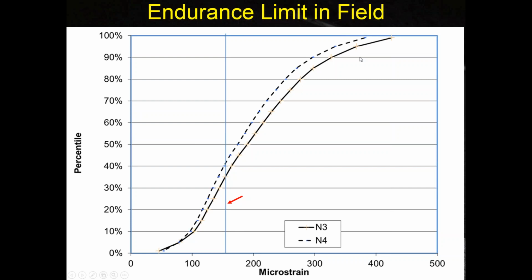If I'm on the right-hand side of it, it means I have an expectation that there will be bottom-up fatigue cracking at some point in the future. So we think about this control as being the break point between, on the left, pavements that don't crack, and on the right, pavements that do experience bottom-up cracking. I'm not sure if that answers the question or not, but I'll circle back to that as I get into the design software.